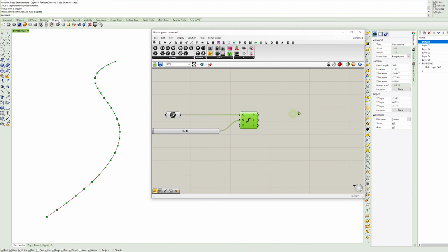Now, if we want to, we can just simply type in move. And this is going to ask for geometry to come in and T for transform. And you can see if I hover, that icon right there means vector. So we need a vector. And I just want to move these vertically. So keep it pretty simple. For a challenge, we'll talk about a challenge later. So just type Z for unit Z, and this is going to move it vertically.